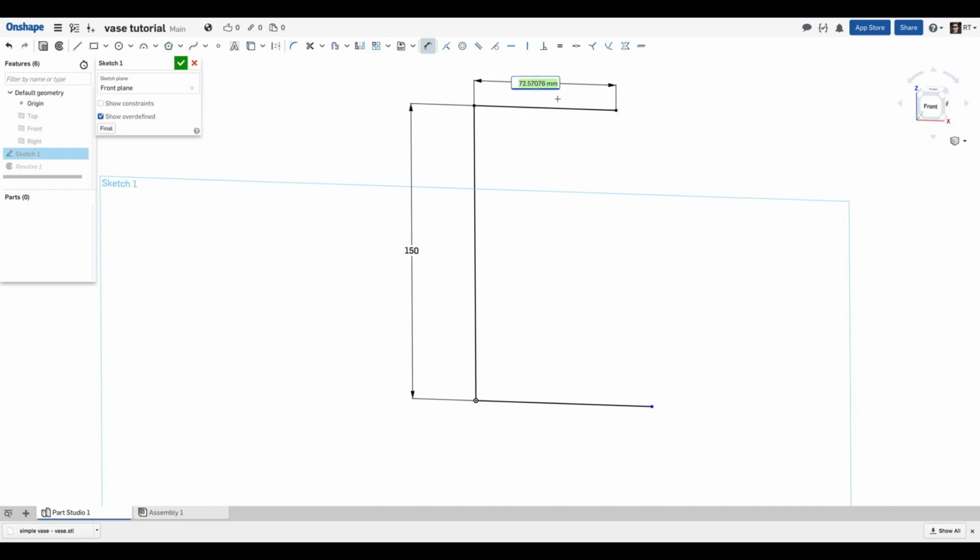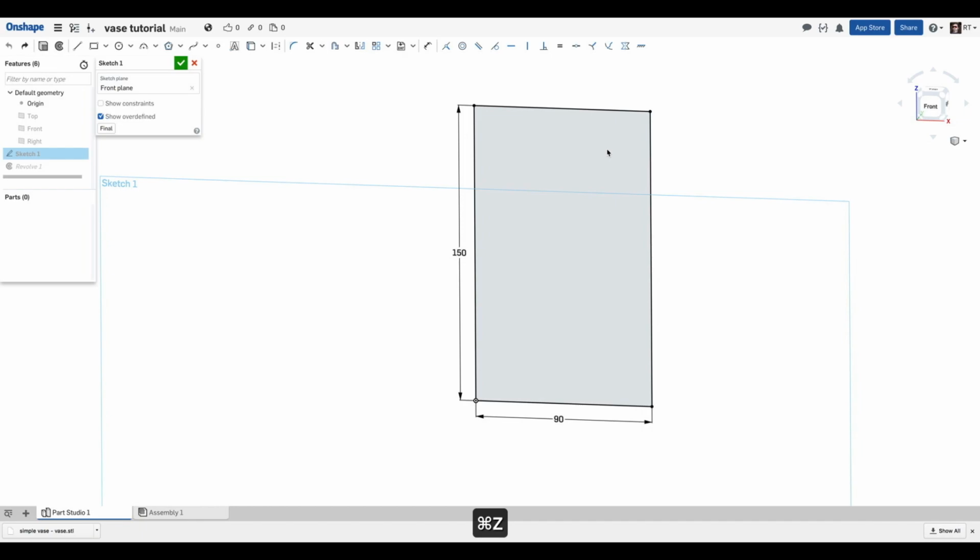Select the line, we could type in a dimension, 80. I'd have to define this one down here as well because it has no reference for that point. Select the dimension tool again. We can then use this to adjust this. If we move near this point, we could have it line up with that. It'll give us a reference point. And then if we change this dimension here, double click 50, it shortens that. But to avoid that altogether, we can undo this. Get back to our line here.